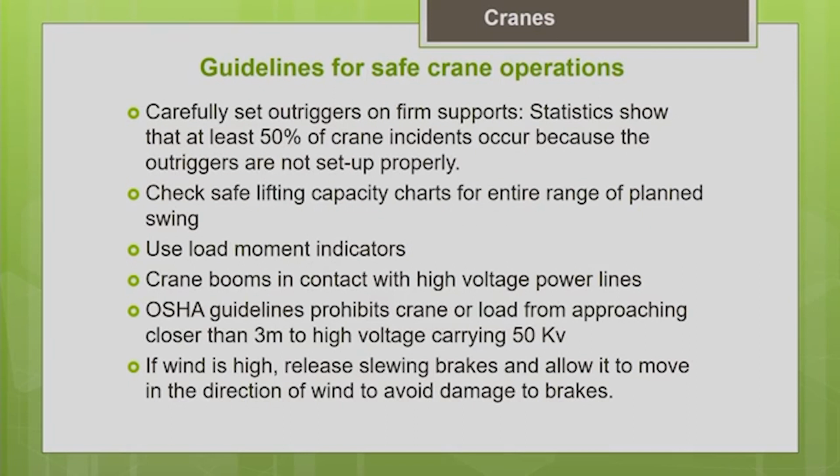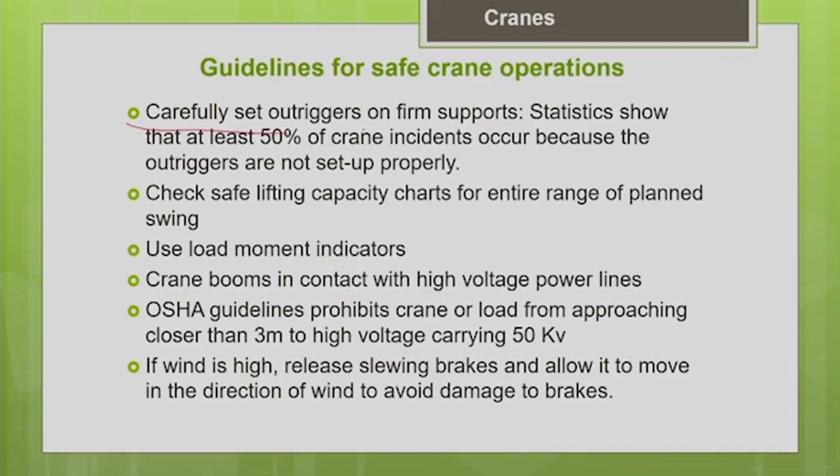There are also some guidelines given for safe crane operations, because you know that there are so many accidents related to cranes reported very commonly. That is why we should follow some safe guidelines when you operate the crane. Carefully set the outriggers on firm supports, because statistics show that at least 50% of crane incidents occur because the outriggers are not extended properly.